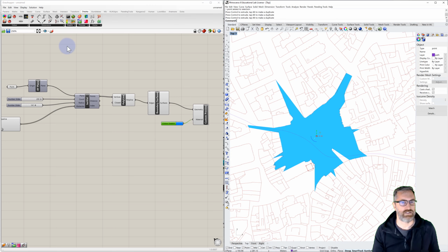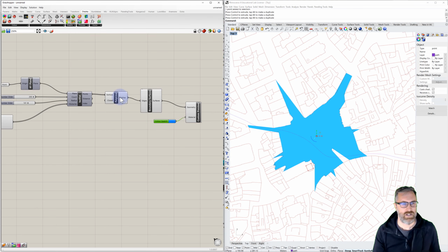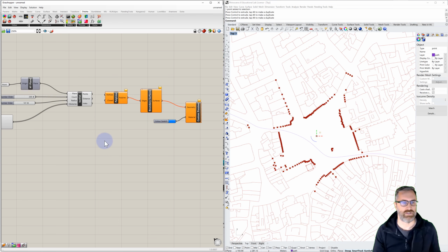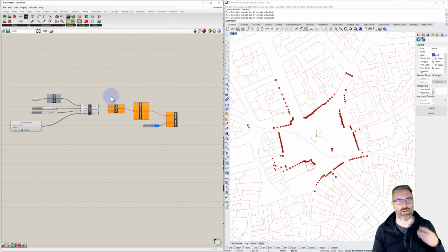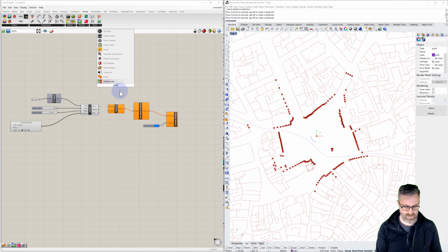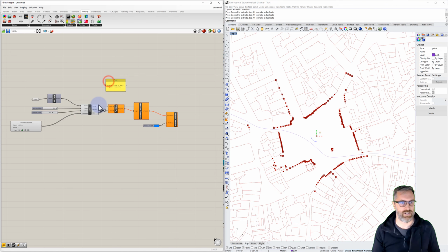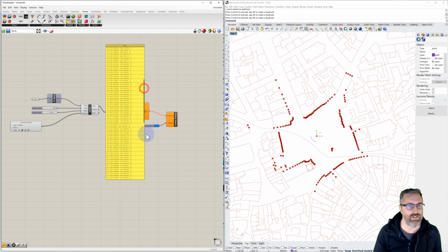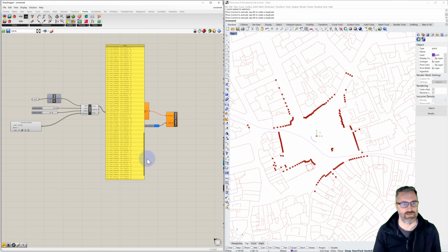So we'll look at our lists, and here let's disable our polyline for a second. We'll turn back on our Isovist view from those points. Here is a way to work through this process rather than me just telling you how to get to the final product. I want to share a couple of steps related to this. So here's a panel with a list. This list has, as we could probably guess, 200 points from 0 to 199.